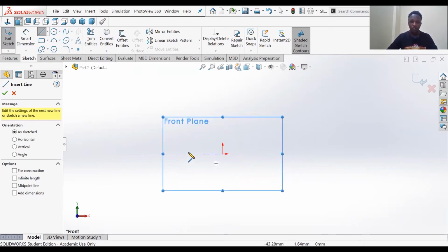It's the only fixed and defined point. Whenever you do a 2D sketching without relating it or starting with the origin, it is not going to be fully defined. Now I'll be explaining about how we can define our sketches as we proceed in the video.